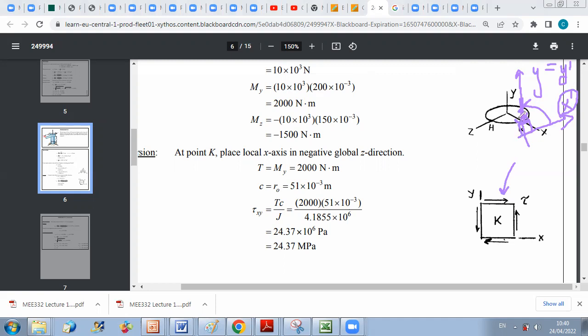Okay, so xyz is the frame given in 3D, but since you have an element and you want to compute the normal and shear stresses for this element, you can take a local 2D frame. You can name them, if you don't want to confuse them with other axes of the 3D frame, x prime, y prime, for example. So you just have to plot your element of interest. And once you plot it, you consider two axes, x prime, y prime, in a way that you rotate from x prime to y prime in the counterclockwise direction.